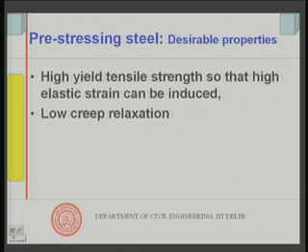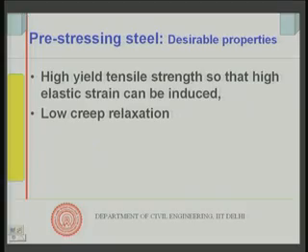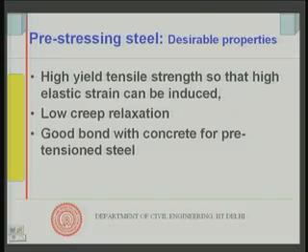We have seen that in restrained situations there is relaxation in the case of concrete; the same thing happens in steel also. So, it should have low creep relaxation, otherwise there would be high pre-stressing loss. So, these are the desirable properties of pre-stressing steel. It should have a good bond with concrete for pre-tension